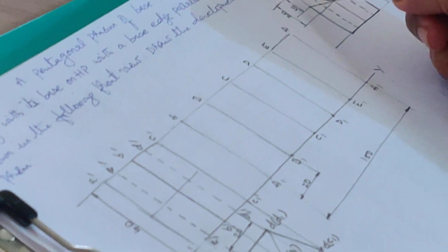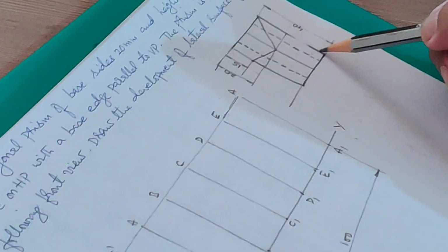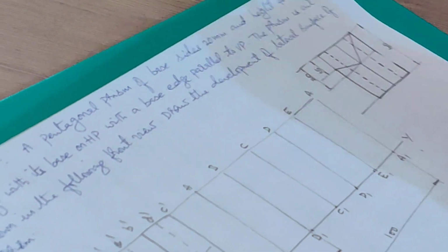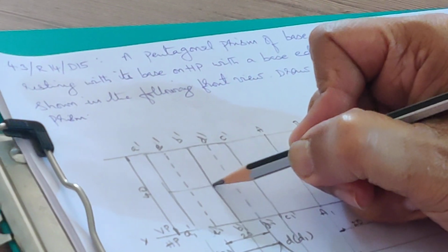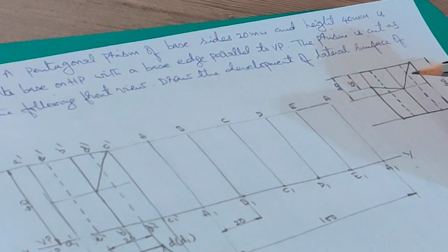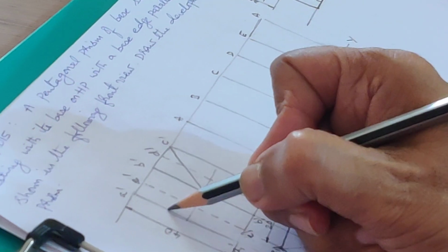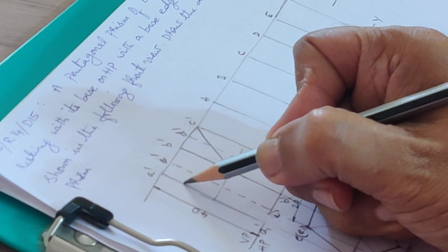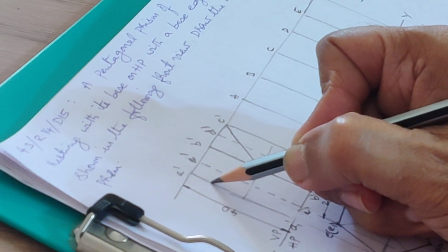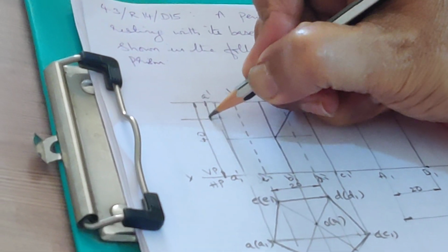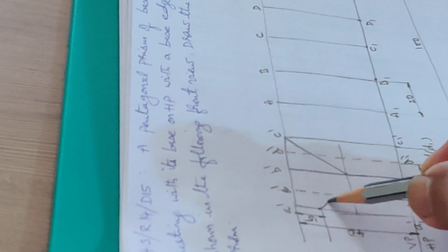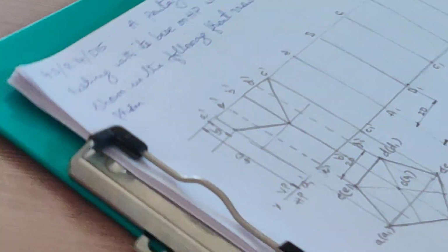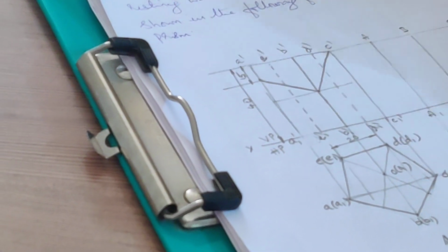Exactly, it is half the height. You can see here, this is 20. The total height is 40. This height is given as 20. So how is the cutting plane coming from the corner to the midpoint? This is how the cutting plane is coming, and then it is changing its direction, moving like this. From the top, mark a distance of 15 mm. This distance has to be 15, and then this is how the cutting plane is proceeding. Okay, this is its path.